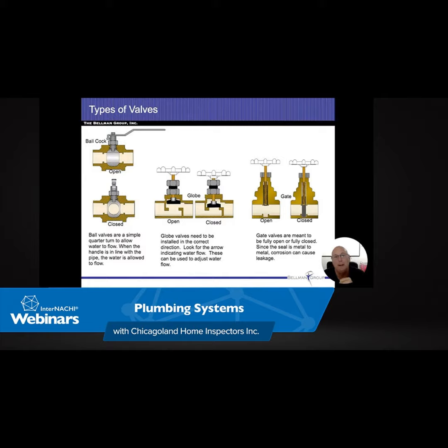Those blue and red escutcheon plates that are on the top of the water heater where the pipes go in, I do want you to take note of those. Whenever we see backdrafting from a water heater, those are the first things that usually end up melting. So if you start seeing them deformed in any which way, it's a pretty strong indicator that that water heater has or is backdrafting. If they've been removed and cleaned up off the top of it, we really should start getting suspicious. Most people aren't going to remove those unless they're trying to avoid something that we would find or something that would be called out.